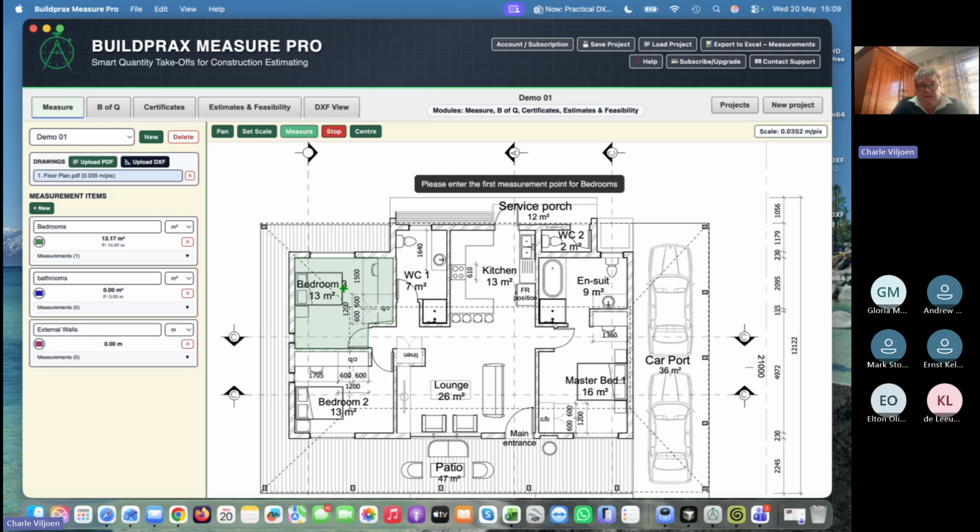And let's say, for instance, this was a duct or something. You want to deduct an area from a measured area, so you put in a deduction, and you measure that area. Now you open your measurements, and when you hover, it will show you where it lights up. As it lights up, we go to the plus minus, and we make it a minus, and it will subtract it.